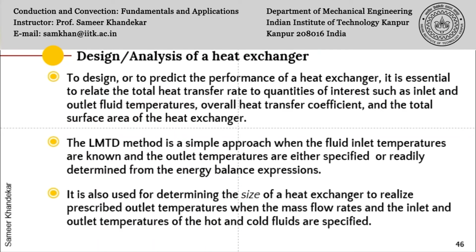So what do you mean by design or analysis of a heat exchanger? To design or to predict the performance of a heat exchanger, it is essential to relate the total heat transfer rate to quantities of interest such as inlet and outlet fluid temperatures, overall heat transfer coefficient, and the total surface area of the heat exchanger. So when you do the sizing problem, you are actually predicting the surface area, what will be the total area required, or what will be the length of the tube required to attain a certain heat transfer.